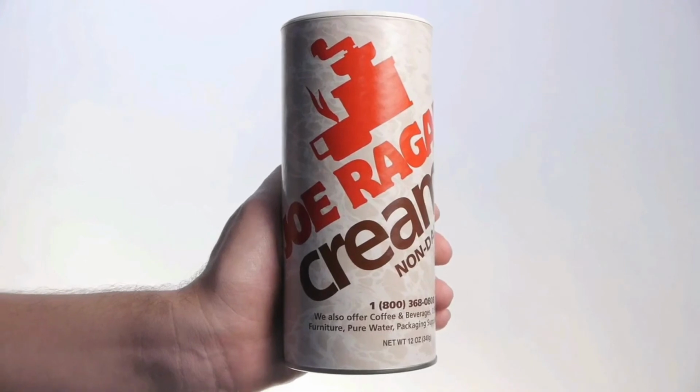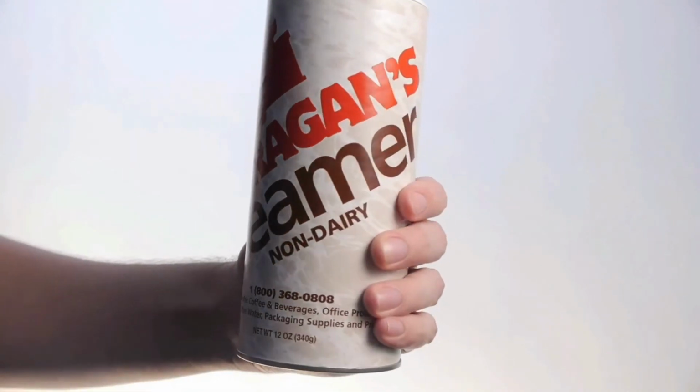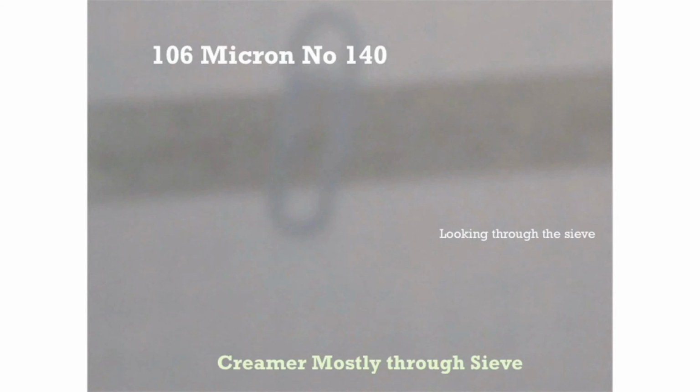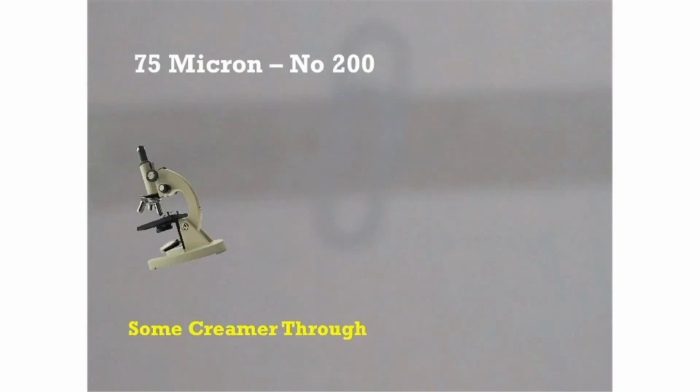I'm sure that many of you are familiar with coffee creamer, the artificial cream for coffee. For our next illustration, we loaded a scoop of creamer on a 120 micron sieve and shook it through. All of it passed. At the next sieve, a 106 micron sieve, most of the creamer passed, with a small amount being retained, some particles larger than a 106 micron, but smaller than 120 micron. At the 75 micron sieve level, almost no creamer passed through, telling us that the remaining creamer consisted of particles larger than 75 microns.